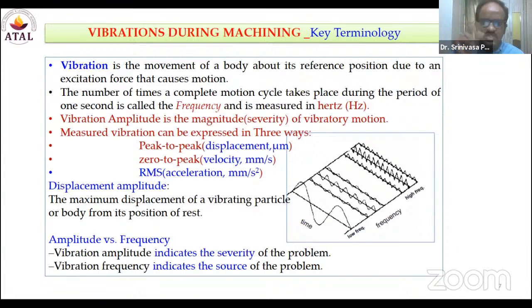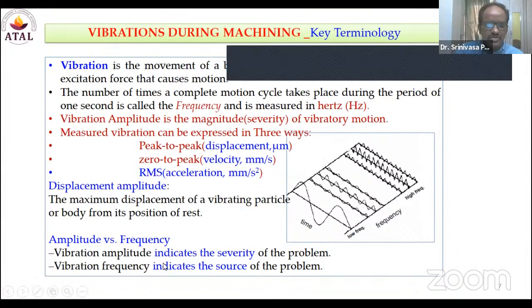Now, there are 2 important aspects to be remembered forever if you are working in vibration. If you are interested in anything related to vibration, remember these 2 statements forever. Vibration amplitude indicates the severity of the problem. If you consider this from peak to peak, it is definitely going to indicate the presence of the vibration, and at the same time the severity of the vibration.